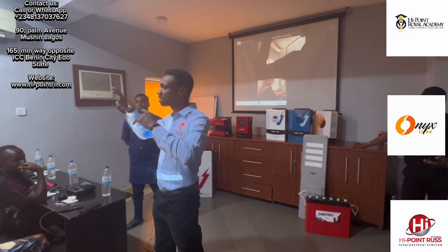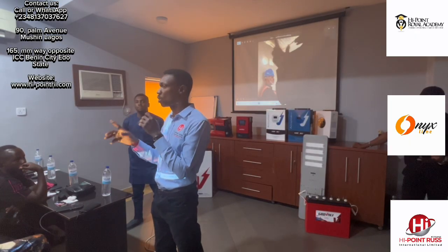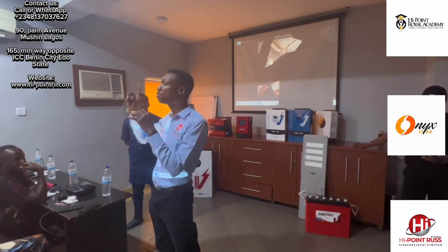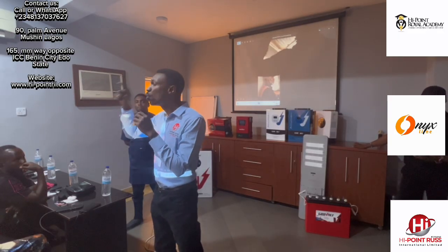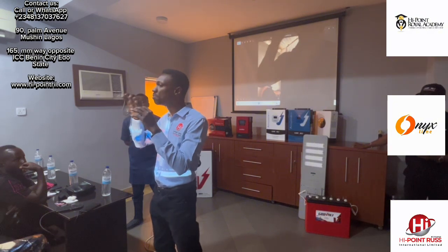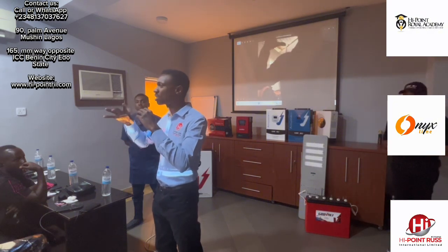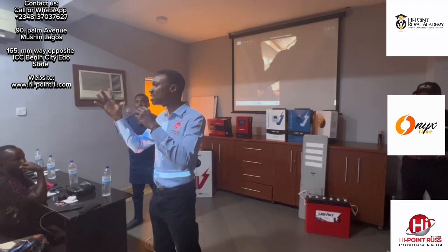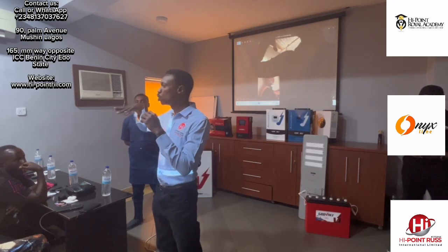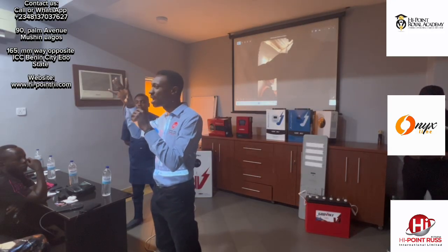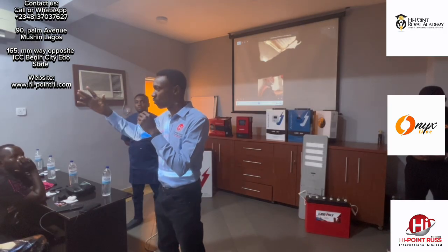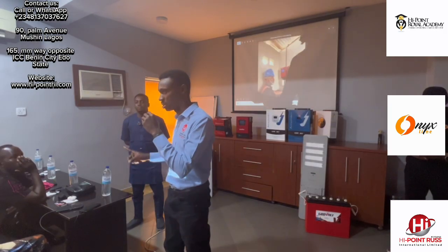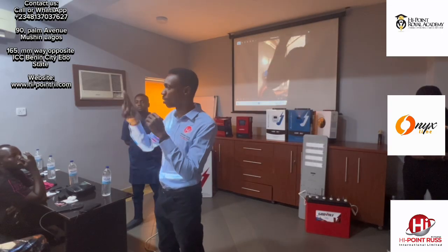If the voltage is high from PV, that is a problem. Although I have seen some people make the mistake of putting in the PV first, but the voltage was low, maybe on an evening or very early morning, when the total PV voltage may not be very high. Still, you have to follow the standard of operation. Put in your battery first before your PV.